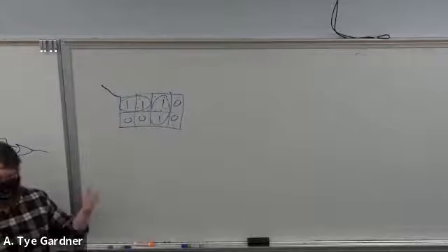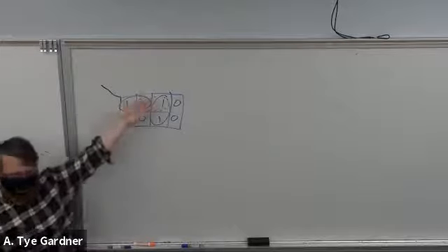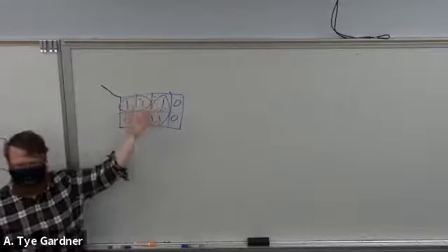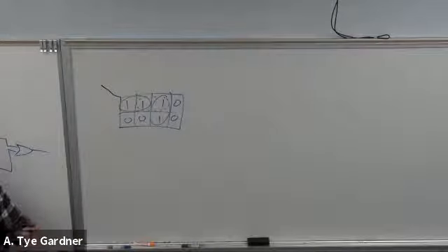Part B, how would you prevent a static hazard in that K-map? You would have a circle, right? You would make sure that there are no 2 adjacent ones unless they share an implicant. So we just add it.